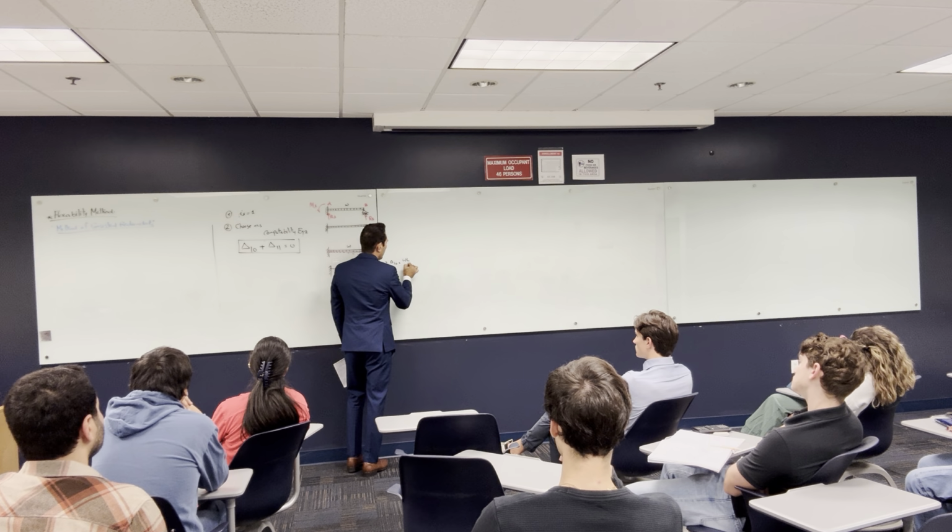If F is equal to 10, I'm going to multiply this by 10. If F is equal to 20, I'm going to multiply this by 20, right? So if you have 100 ton here and 1 ton makes 1 centimeter displacement, then 100 is going to make 100 centimeter. Okay? So basically, I can write the compatibility equation that way. I can say that delta 10 plus F delta 11 equal to 0.